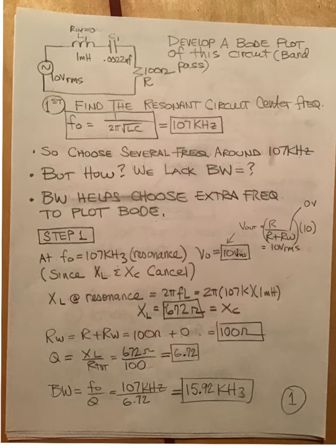Which is this one right here. And it's an RLC circuit with the voltage taken off of the resistor. It's always taken off the resistor if you're building a bandpass of this style. And the output voltage is from here to here, plus to minus, from top to bottom.